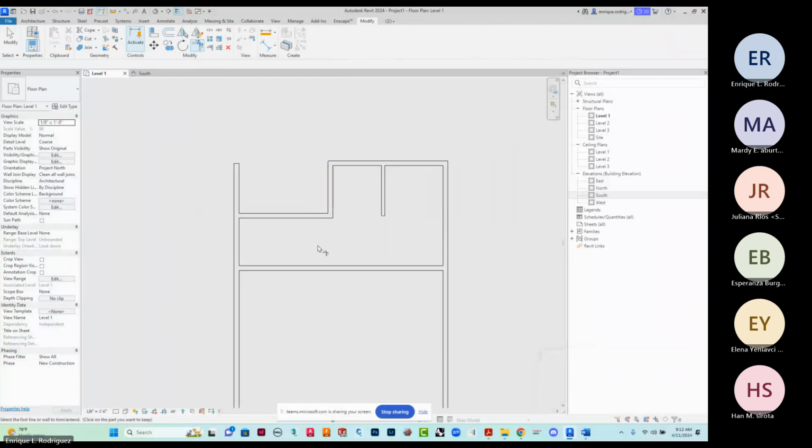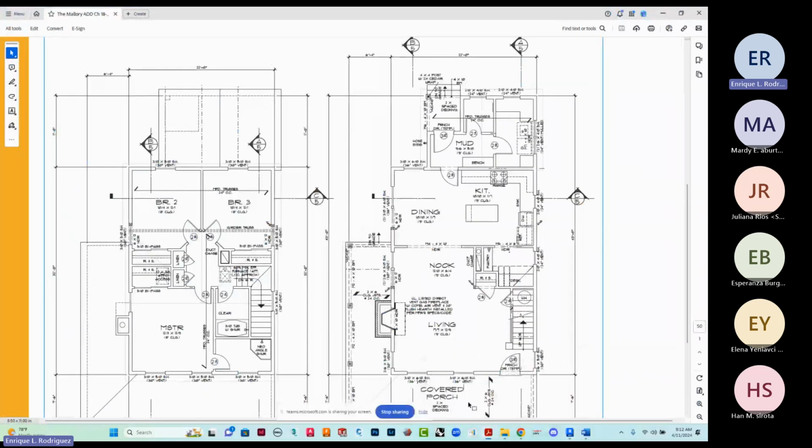All right, so now looking at the plan again, the only thing I have is another break coming down in here somewhere. Again, I can even fillet this one, but I'm going to save that command because I'm probably going to need it down in here. Now, this one really doesn't have much information for that, but I know that I have a door that I need to fit in there. So if I take a look right in here, this is a 3.0 door, a 3-foot door, and I want enough return on each side.